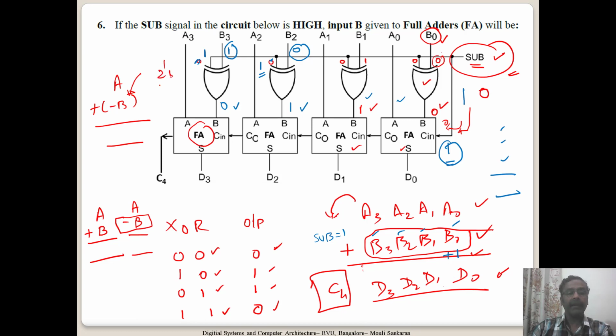I find the 2's complement. Now how do we get the 2's complement? We complement the bits, whatever is coming in, and then add a 1 to it, and then we get the minus B value. So let me give an example. Now suppose I have a value which is 0, 1, 0. I want to perform an A minus 2 operation, where A is a 4-bit value. I want to perform a minus 2.